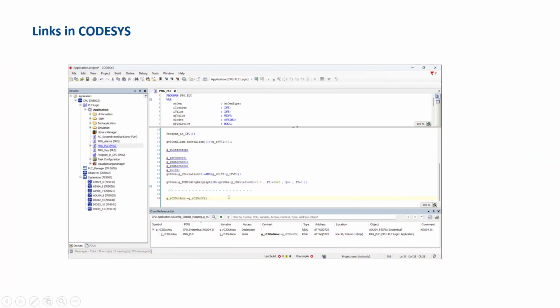The generator is working, and in principle, the process steps are also functioning. However, the set points of the generator available in CODESYS are not yet linked to the control channels. In addition, the actual values of the controllers are not yet available to the generator and therefore cannot be displayed in the generator image. I will now link the actual and set point values in CODESYS. But I still have one thing to do.